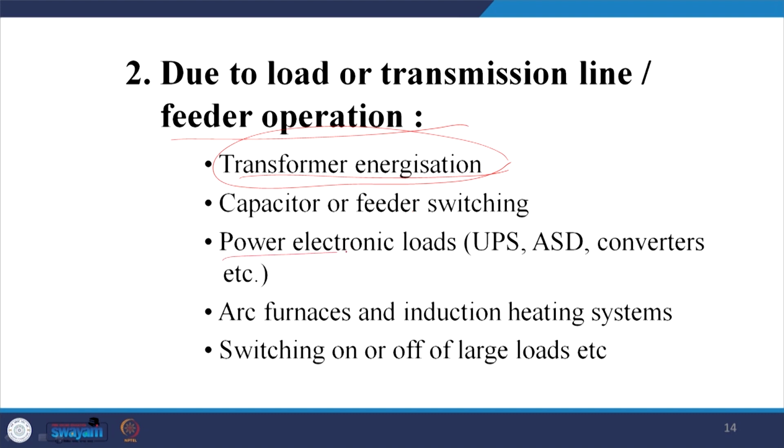And thereafter, power electronics loads. In power electronics loads we mostly have a voltage source, and these loads are generally constant impedance loads, and these can be constant power loads. So, if the voltage is low it will take more current, and thus it has more problems from the stability point of view; it will take you to a more unstable region, that is another issue. So, it can be an uninterrupted power supply, which we very frequently use with our desktop.